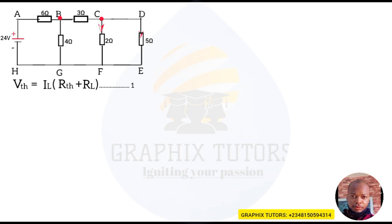So we start. What's the first thing we have in our formula here? VTH. So we say calculating for Thevenin voltage. That's the first thing we're looking for. And when you are calculating for Thevenin voltage, it means that you are going to remove the resistor you are focusing on. You're going to remove the resistor in which focus is laid upon, right? And that is the 2 ohm resistor here.